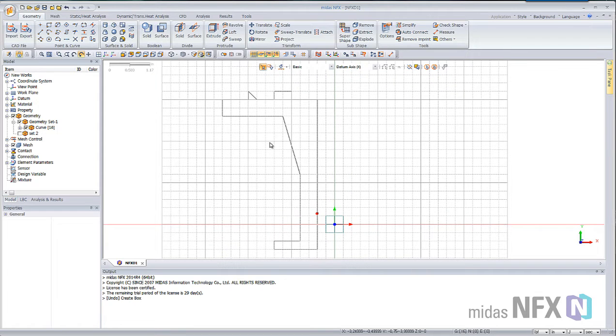So you have different types of operations to handle those lines. Let's say if you want to extend a line, you can use the extend curve option. If you want to trim a curve, you can use trim. You can intersect edges together. You can make a wire so it's easier to handle. You can merge curves together to create one line, or you can break curves. So I'll not detail all that.